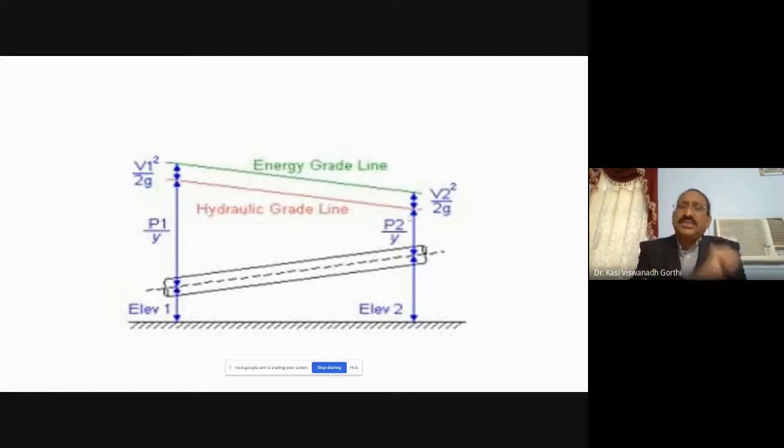But there is an assumption while deriving this Bernoulli's equation. We said that the flow is ideal. If the fluid were to be real, what would be the problem? Since the fluid is real, it possesses the property viscosity, which offers resistance to the motion of this fluid in the form of layers through this pipe.